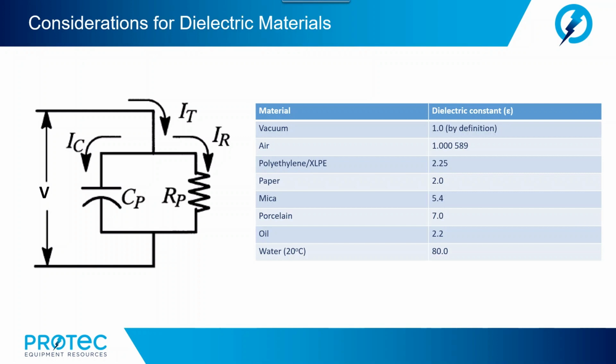Another consideration is the dielectric constant, which is the extent to which a substance concentrates the electrostatic lines of flux. Substances with a low dielectric constant include a perfect vacuum, dry air, and most pure dry gases, such as helium and nitrogen. Materials with moderate dielectric constants include ceramics, distilled water, paper, mica, polyethylene, and glass. Metal oxides, in general, have high dielectric constants.